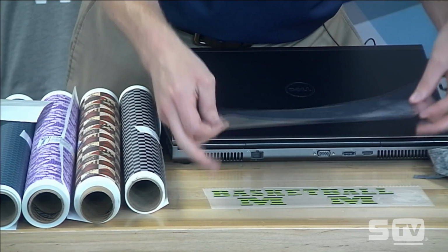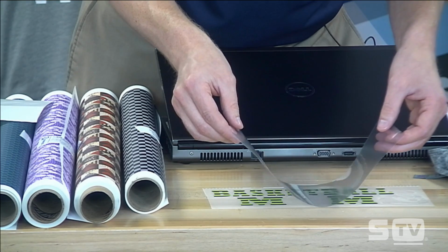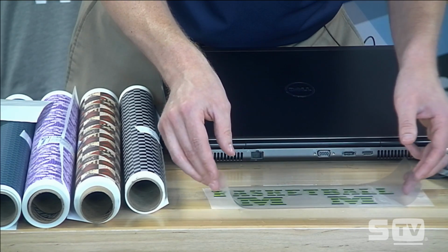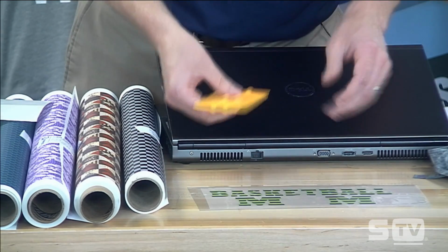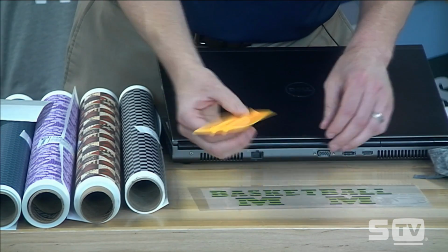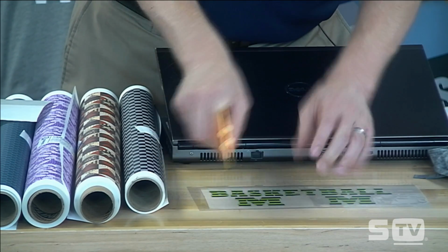The technique basically is you bend your mask in the center, okay? Get a nice view of that and just sort of let it fall and work from the center out. Just drop it onto the pattern. Then you take a credit card or a squeegee and you basically take it from the center and push the air bubbles out, applying pressure.